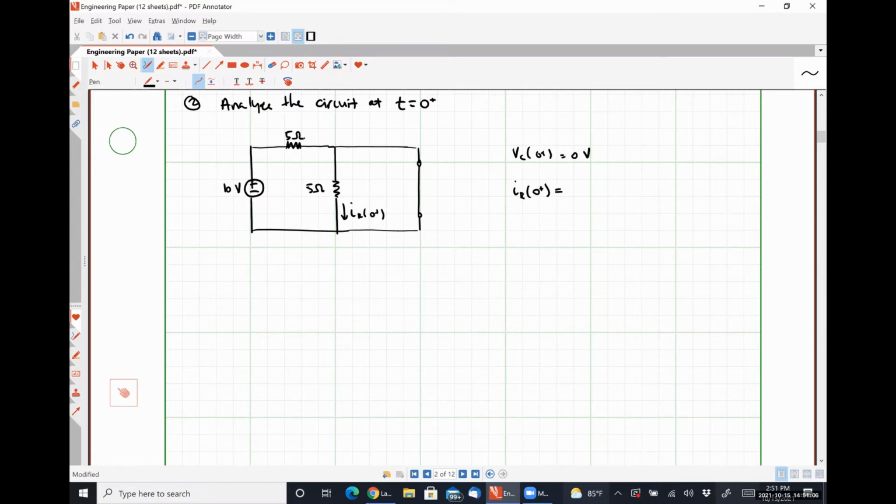So I had 10 volts in parallel with a 5 ohm resistor, everything is A-OK, in parallel with a short circuit. By definition, the voltage drop over a short circuit is 0 volts. So I can't have 0 volts across my 5 ohm resistor and 10 volts across my 5 ohm resistor simultaneously. Does that make sense?